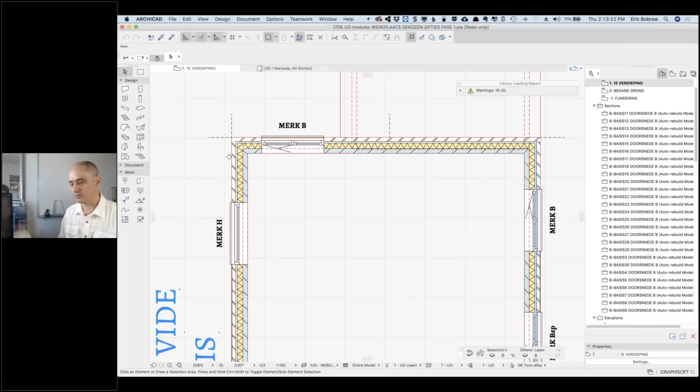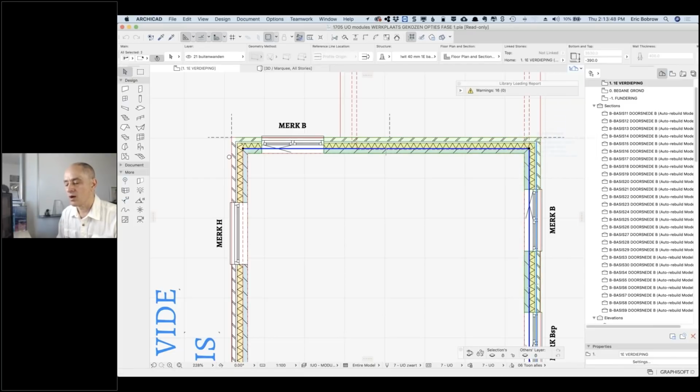Sometimes it had to do with the floors being not beams but walls, and they were interacting with each other. So I had to give them a slight offset. And another thing that was causing the problem was that this wall was slightly tilted. So I've solved all the problems, but yeah, it would be nice to know quicker ways to see where things are going wrong.